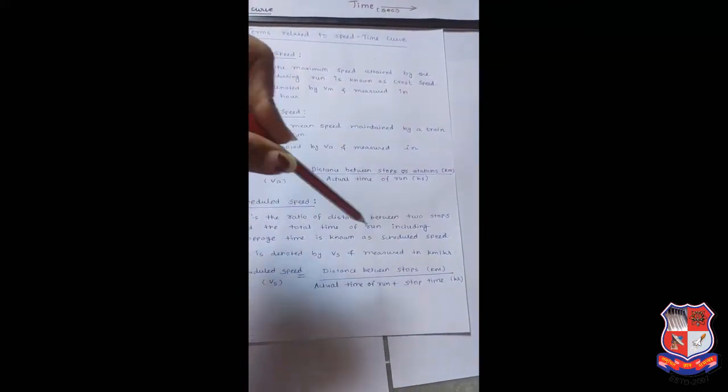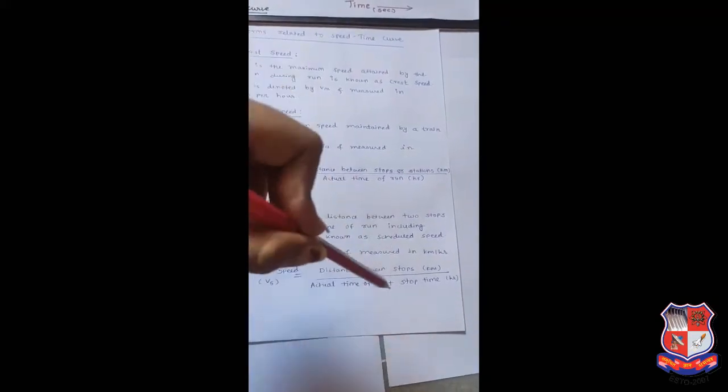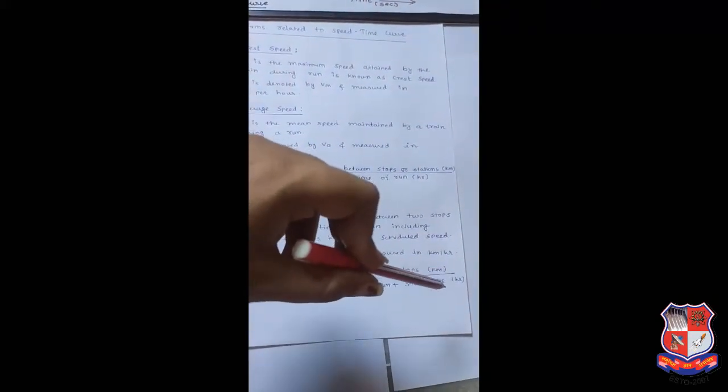Okay, so see the difference. In the average speed equation, the numerator is the same but the denominator is different. In both, the numerator is distance between stops or stations in kilometer, and in average speed we only consider the actual time of run, but in schedule speed we also consider the stoppage time. So the equation of schedule speed is equal to distance between stops upon actual time of run plus stop time. Okay,